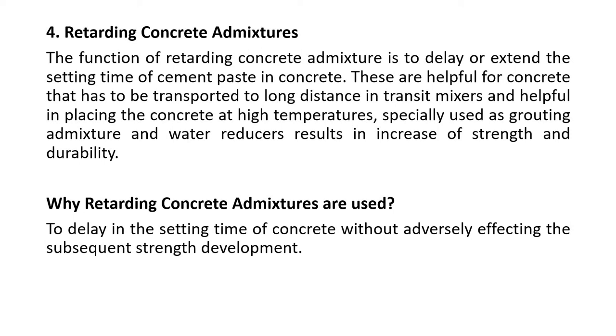Retarding concrete admixtures. The function of retarding concrete admixtures is to delay or extend the setting time of cement paste in concrete. These are helpful for concrete that has to be transported long distances in transit mixers, and helpful in placing concrete at high temperatures.